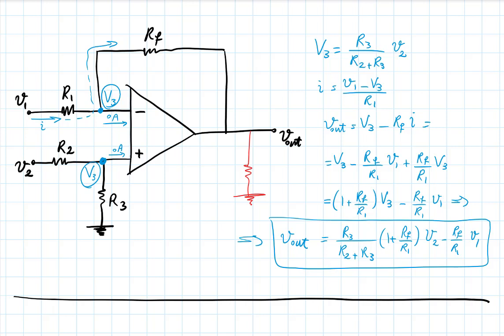Now, what does that say? Did anything change in the op-amp at all? Is there any change in the circuit? I just suggested that V out is not going to change, but is there anything else in the circuit that did change? There will be current. You see, before, if I didn't have that extra resistor, this current would have gone all the way like this, had to go back to the op-amp.